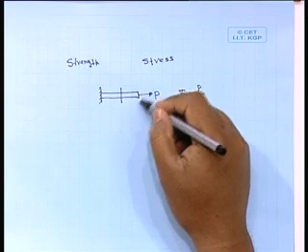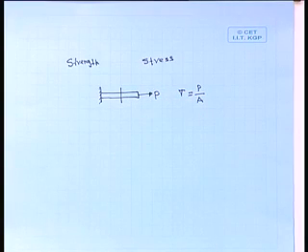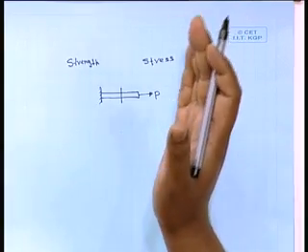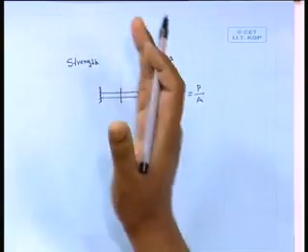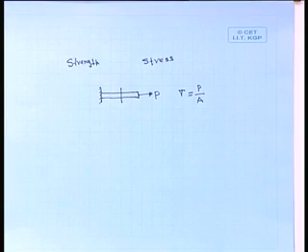Here at the point of application, the load may be acting on a small area, but gradually that load will be distributed over the entire cross section. So, there might be a localized problem at the application of the load, but within a short distance it will be stable. The load will be distributed over the entire cross section throughout the length of the member.